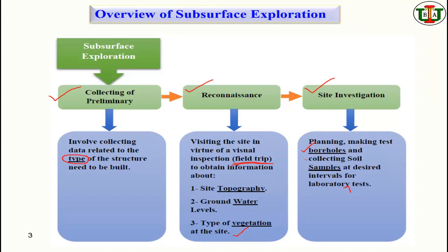Okay, so you go for a field trip, because before going to the field, you don't know the scenario of the site: topography, groundwater levels, site vegetation, or any obstacle in the site that might disturb you during testing. Suppose you decided to make a borehole, so you need to collect samples for testing in laboratories, right? For that reason, you need to decide on different methods. There are some different methods we'll be discussing.